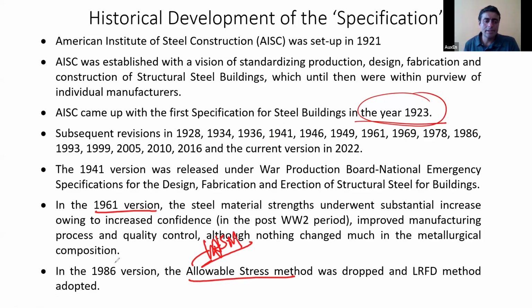But in the 1986 version, this ASD method was dropped, and a limit state based approach was introduced, which is called the LRFD method, load and resistance factor design. Now, because you had a better understanding of the material, of the section behavior, and of the local and global buckling issues.